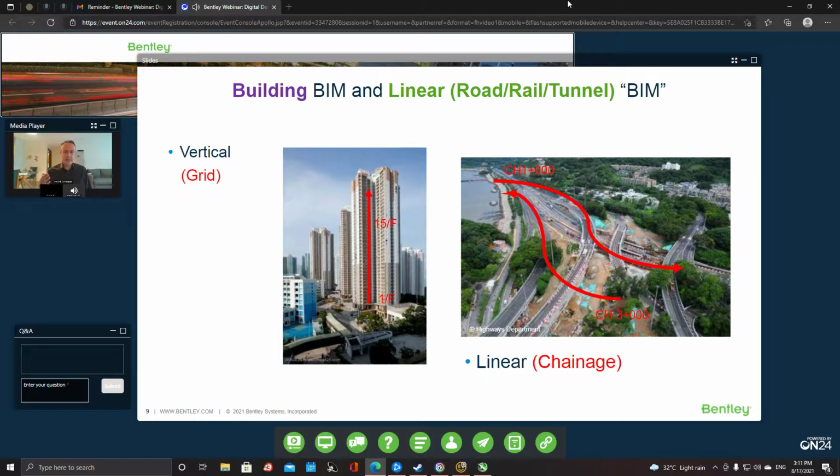The chainage-based, or you could call it alignment-based, approach is different, where you're following an alignment, and these could, of course, be several alignments that merge, or there could be forks and so on. They go up and down, and there's radius, there are straight parts, and a clothoid as a transition, for example, as on the right-hand side.